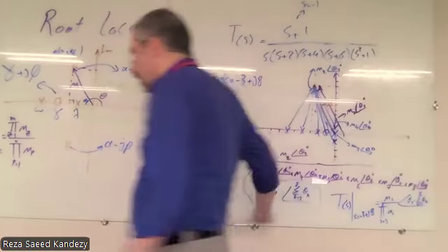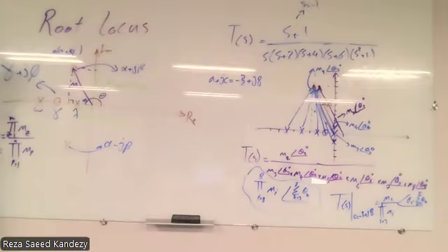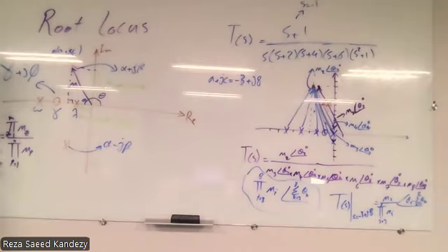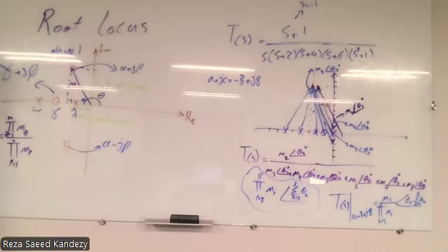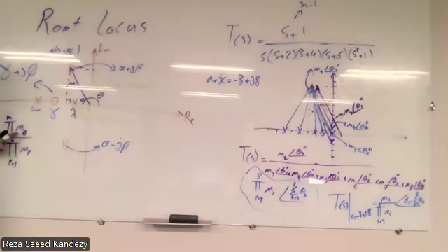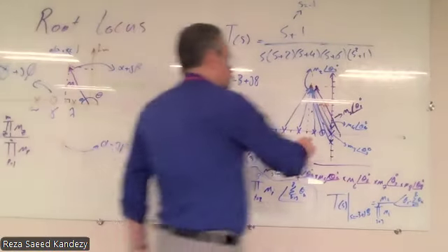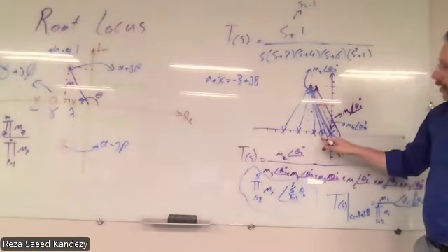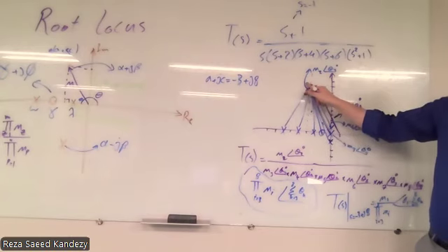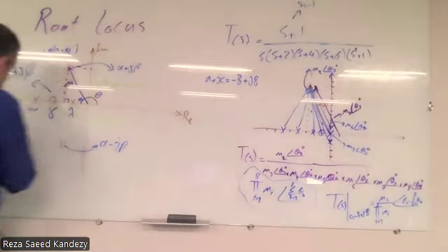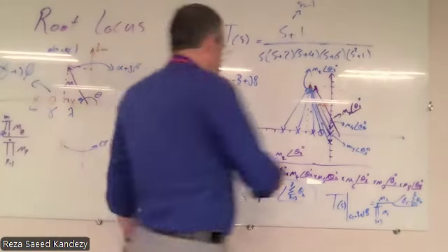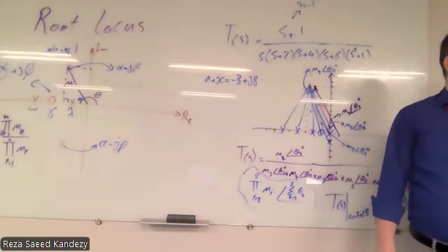So using that example, we find out that we can actually calculate the magnitude of our transfer function in a specific point, okay, using the magnitude of the vectors from the zero or zeros, connecting the zeros to that specific point that we want to see, okay, divided by the multiplication of the magnitude of the vectors that connects the poles to that specific point.